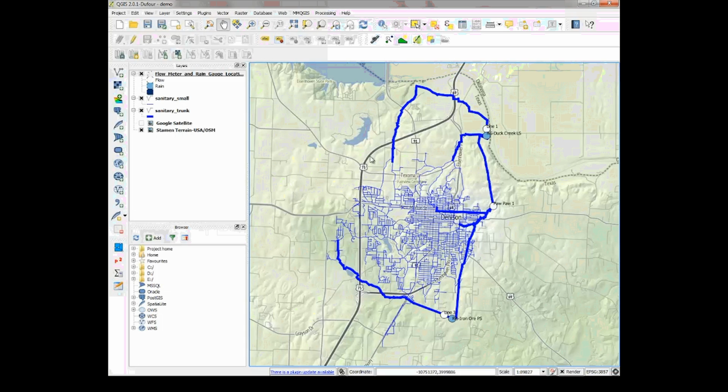other things that are useful would be the amount of linear feet of sanitary sewer system that feeds into that system, as well as the actual area of the sewer shed. That's principally useful for normalization. So if I have performance indicators based on volume of inflow or infiltration or the combined wet weather response per surface area or per acre, that's something that a utility can use to help manage and try to set goals. But enough about that. Let's go ahead and just get started with the program.